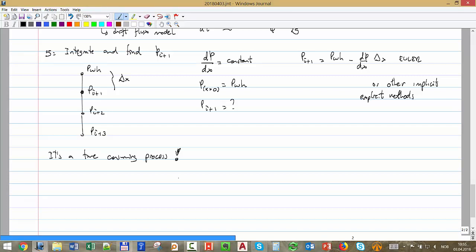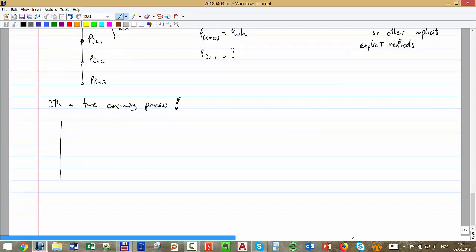Okay, for example, here you have PWF versus Q of oil, and let's say you have the IPR, one equation that looks like that. Then you repeat that calculation: you assume a rate, with PWH constant, and you calculate this bottom hole pressure.